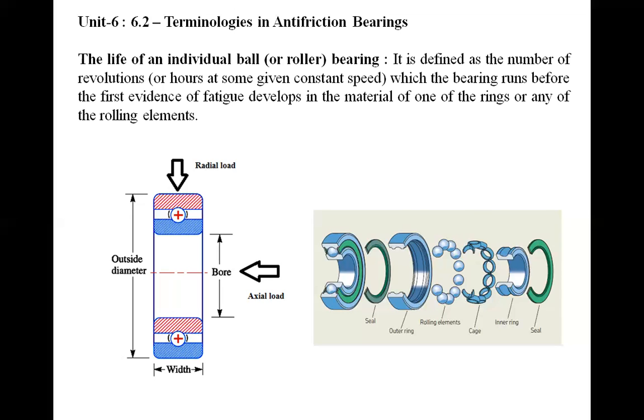As far as loading is concerned, the radial load and axial load are given directly on the roller or ball. When the ball is subjected to such a load, the ball is a rotating rolling element. When the ball is exactly at the bottom side, it is subjected to a high compressive load. When it rotates again and comes to the upper side, the load is released.